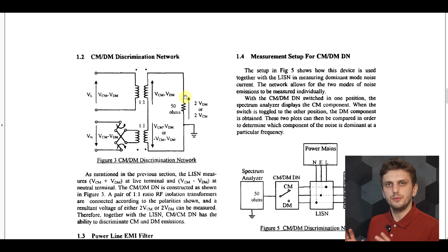Now, there are a few important things to observe here. First of all, since the circuit only uses transformers, it's a passive circuit. So no need for external power supplies. Secondly, since transformers are involved, you can build the transformers any way you like. So in theory at least, you can get this thing to work with any frequencies or any bandwidth. And at the same time, you can work with any voltages. So small voltages, large voltages, doesn't really matter.